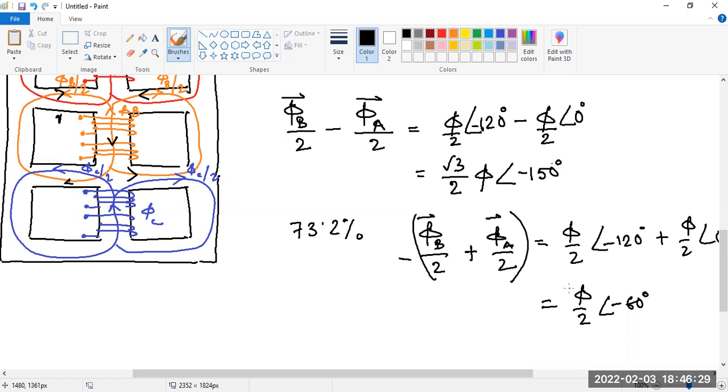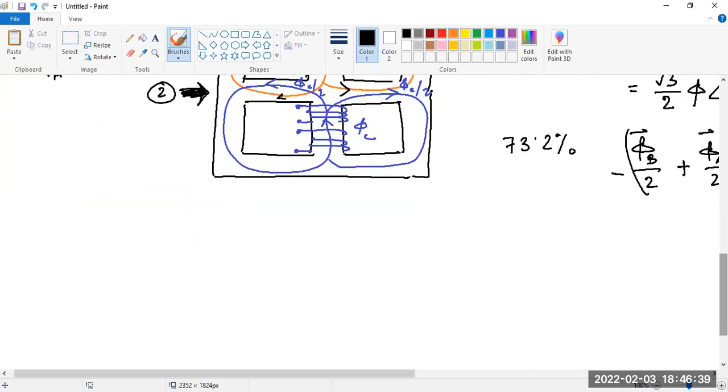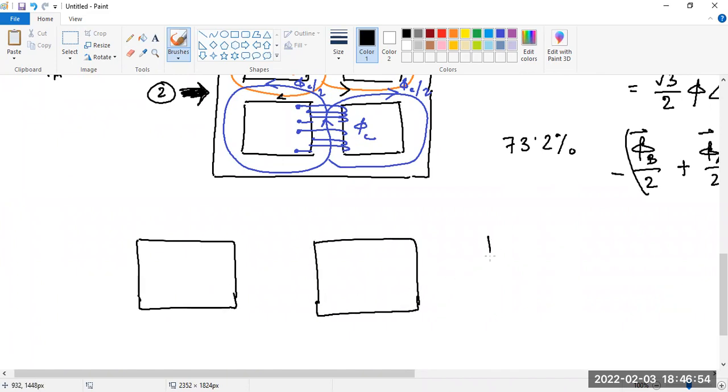So you have understood. So what is the problem with the shell type transformer and why is it called the quasi independent magnetic circuit? If we have 3 single phase transformers, physically they are in different positions, so there is no magnetic linking between them. So this is your phase A transformer. So here the transformers themselves are different.